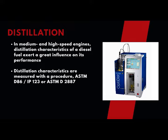So, in this continuous distillation apparatus, the sample is taken, it is heated and the hot vapors are cooled and condensed, and the distillate is collected in a measuring jar. At specified intervals of the volume collected, the temperature is noted, and that will determine whether the product is accepted and whether the product can be considered to be on spec.